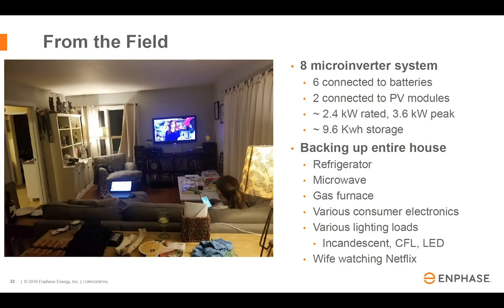And we design that dead band to be large enough to be very easily detectable, but small enough that it's still tolerated by loads for that short duration, because it takes us time to disable that. For us, I think we set it to plus or minus 2 hertz or something like that, but it's completely programmable. It gives us a really nice detection band, while still providing an envelope when you form an island that wasn't predicted or forecasted and your inverters aren't told ahead of time. It sets a band on how wide the voltage and frequency can get. So you get this pseudo seamless transition. I don't call it seamless, because you do get a jump in voltage and frequency.